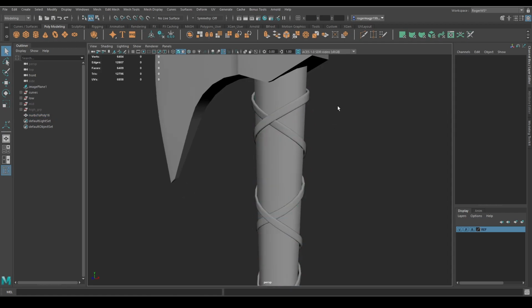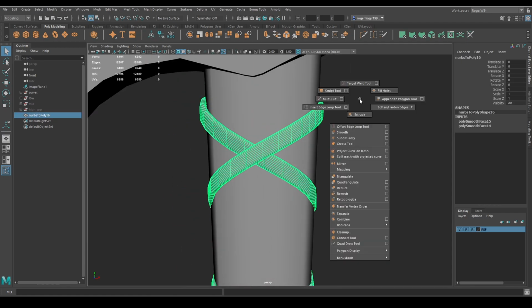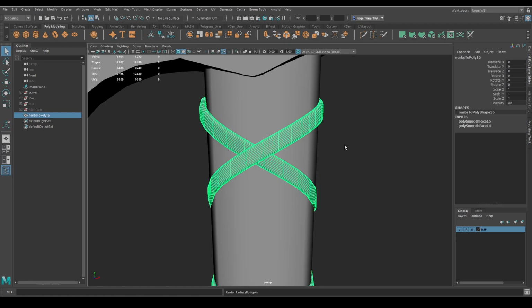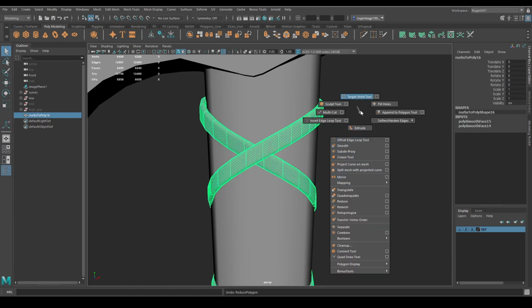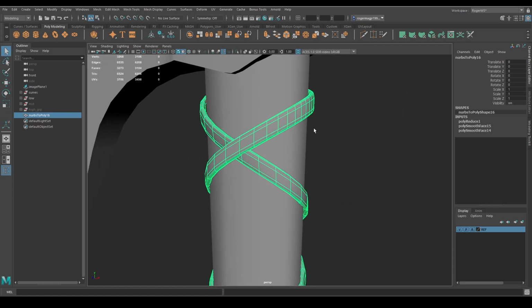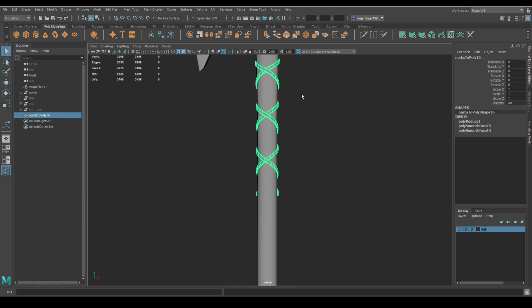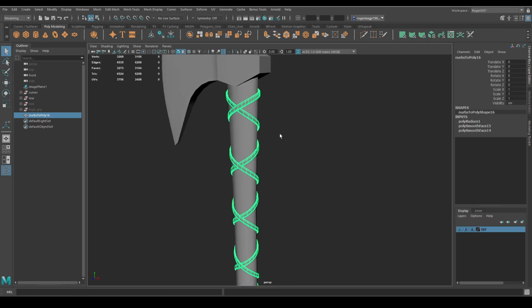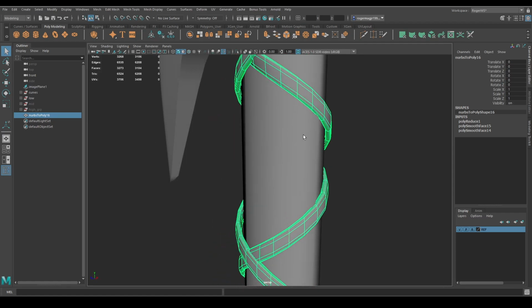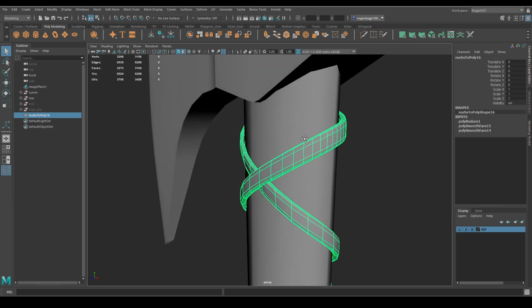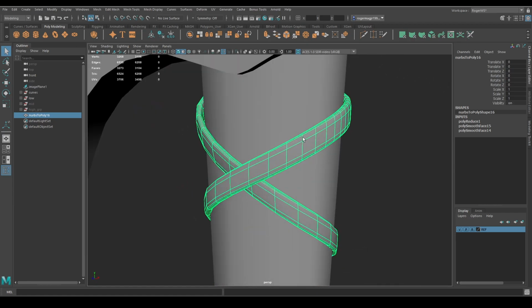So what I'm gonna do now is select reduce, and I closed it before, so I'm clicking shift right click reduce, then percentage 50%, and then click Q to confirm. I know this will add a lot of geometry, but I think it will look nice having this. Since it's just for portfolio purposes or for a video, we're gonna keep it, but we're gonna clean it more.